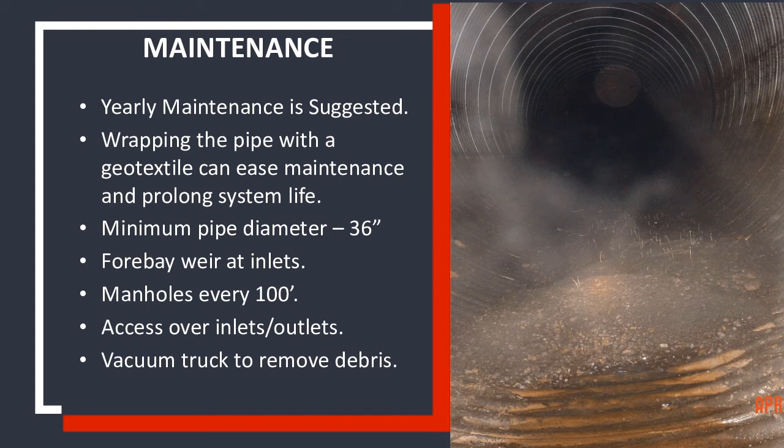And then we always say wrapping these pipes with a geotextile. One, it can ease your maintenance, and two, it can really prolong the life of a retention system. Minimum pipe diameter is very important. If you've never been inside of a 36-inch pipe, you need to try it. It'll change your life. Being a man of average height, I don't like to go into anything less than a 72-inch pipe.